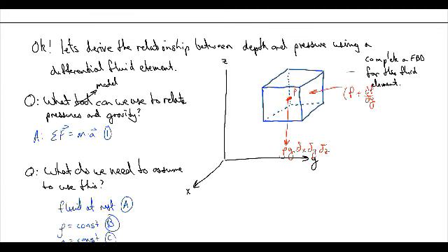In order to get the actual amount of change, we have to multiply the slope by a distance, right? So we're going to multiply our dP/dy, which is our slope, times delta y divided by 2, because we're only going half the way across this cube, right? We're going from the middle here to this edge over here, and this distance is delta y divided by 2.